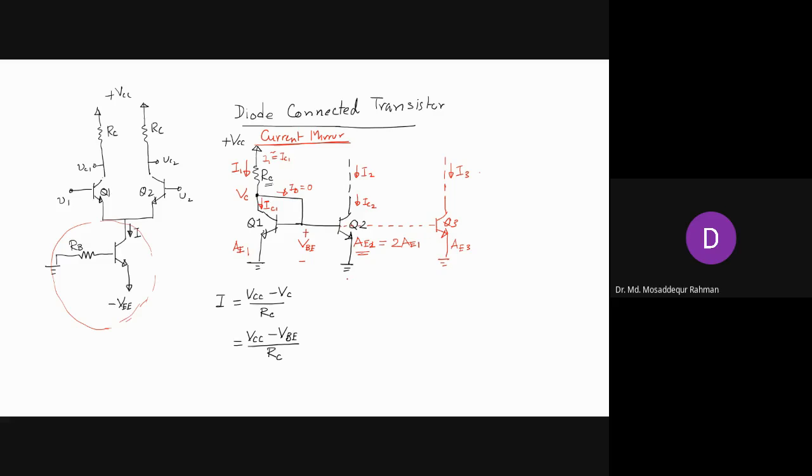As you know, in the first stage we need small current, right? So the area will be small, and the second stage, the gain stage, needs a higher current. Then we need a higher cross-sectional area. The output stage will need even higher current, much higher current. So that will be an even bigger cross-sectional area. Is that clear, guys? The basic concept. Yes, sir. And you need to apply that in your design of the multi-stage differential amplifier, how to design the different current sources.